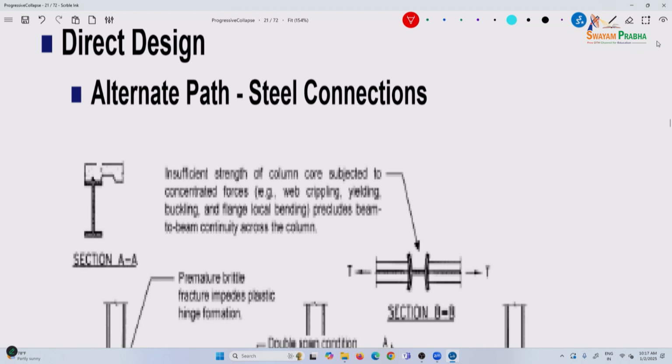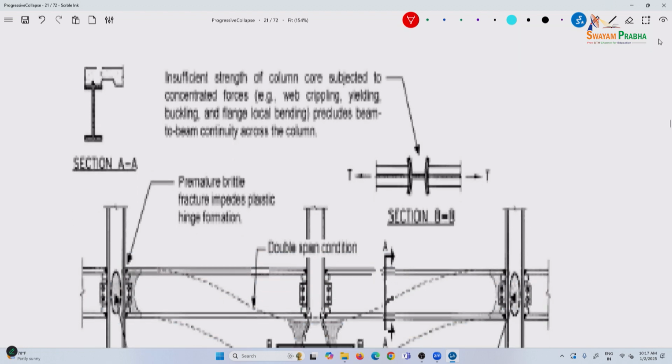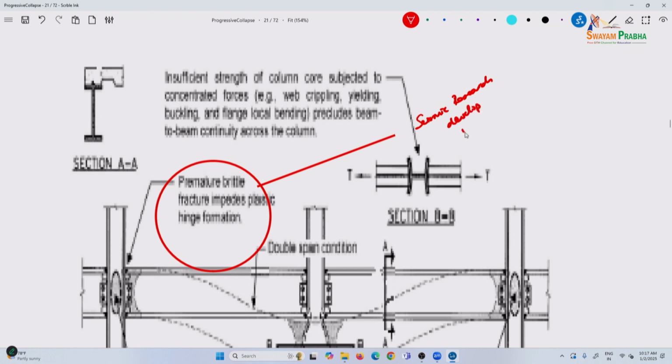Steel connections, these are hard to read. A lot of seismic failures occurred because of welding, the types of welding, types of connection, which changed a lot of connection detailing and moment connections. Seismic research has developed very advanced ductile connections, so look into that.